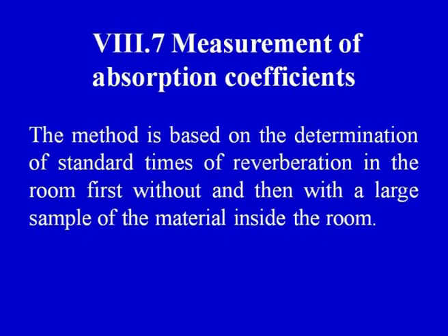The method is based on the determination of standard times of reverberation in the room, first without and then with a large sample of the experimental material inside the room.